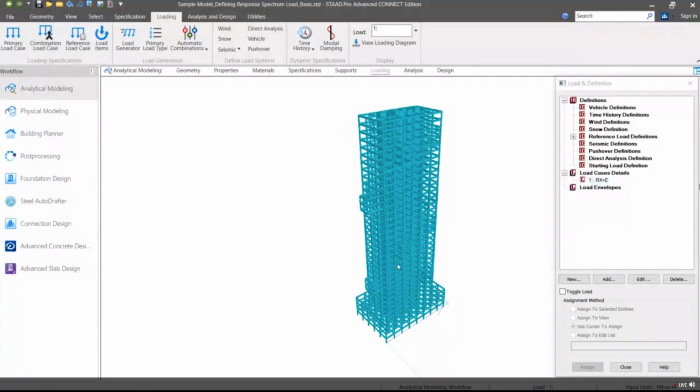This should be repeated for load case 2 and load case 6, considering the response spectral load from X direction with negative accidental eccentricity value. 4 load combination cases are created now for load case from X direction. Same needs to be created for load from Z direction also.